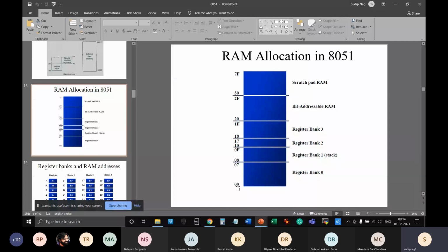Now the question someone asked is how does it discriminate whether the 00 is within the internal RAM or external RAM? So the MOVX essentially disables the read write from this. See, read write signals are going to each and every memory location over here, internally. We don't get to see that in the block diagram, but it is present. I can write anything, read anything from anywhere within this 128 bytes of RAM.